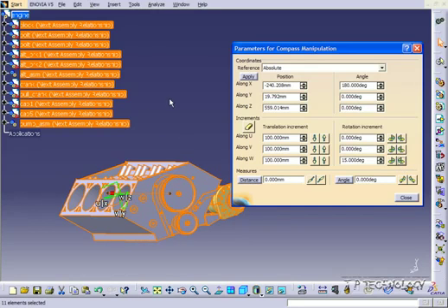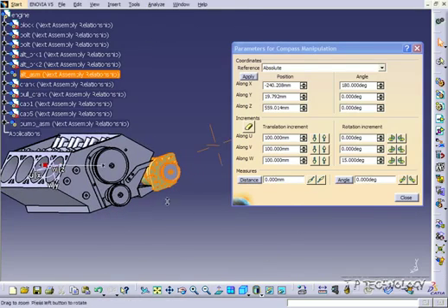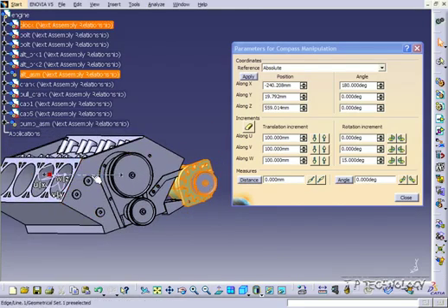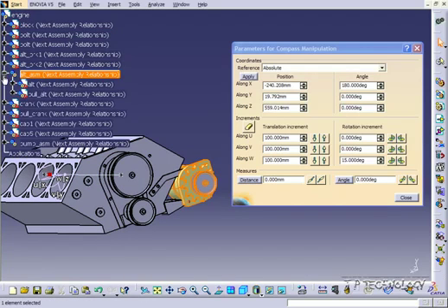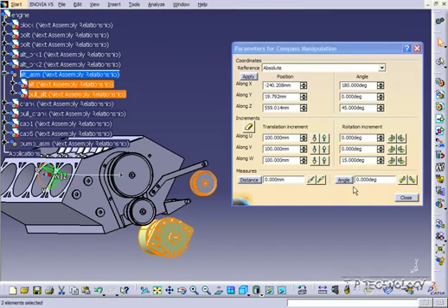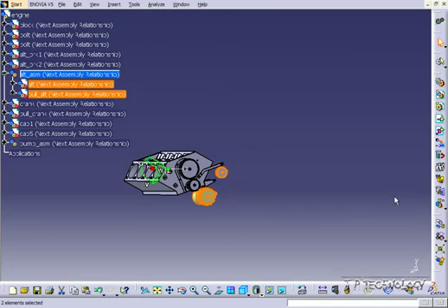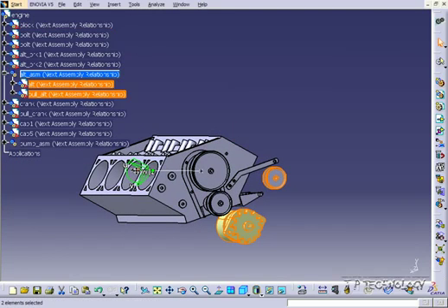And again, we can do this to a smaller assembly. So double click the alternator here. And we're still going to use this as our axis point. Open it up and let's just rotate this one guy. And you can see that only he is rotating. And as we select both, we're able to rotate both at the same time. So again, this works by using this axis that we've created. And this is going to create a consistent axis. So every time we go to rotate, it's always going to be the same result and the same rotation that you get.